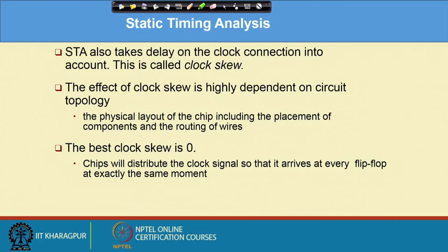So, this is the concept of static timing analysis. And clock skew is an important factor, not only clock skew, but also setup time, clock-to-Q, and T logic. During optimization, what we have done till now is on the combinatorial logic part: we have reduced the timing or the area on those particular paths, but we have not considered the other things associated with the whole timing closure calculation. We will see that in continuation of these lectures.